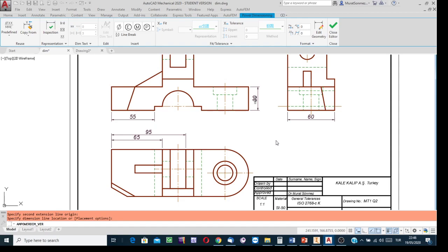It is to say erase. It is the thing to do. Click on the backspace button of the keyboard. I said don't show this dimension, and then write the correct value 32 using the keyboard, and then to have the dimension underlined, click on this facility button.